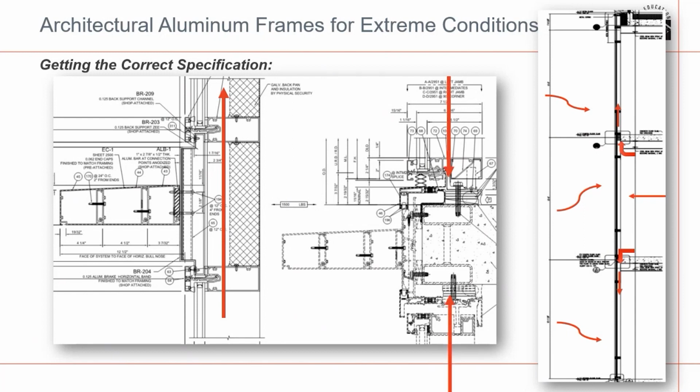Window wall systems don't bypass the slab edge, they're set within it. So sound moving through the frames hits the next slab and stops, and it can't pass from one floor to the next. You look at these two details beside each other, they're designed to mimic the same look. It looks like an aluminum framing system moving up the exterior of the building with sunshades on it.